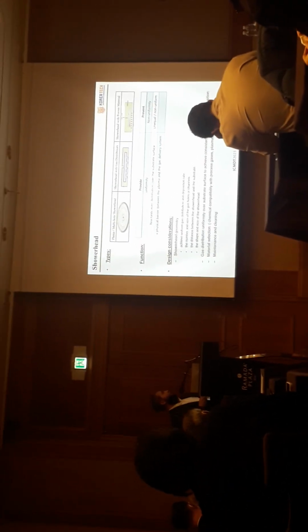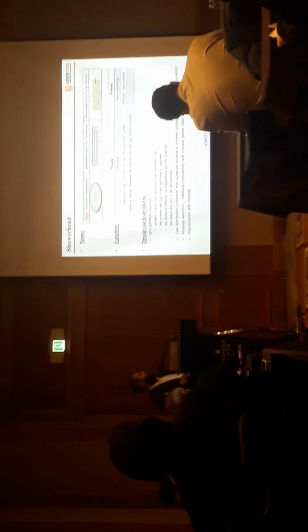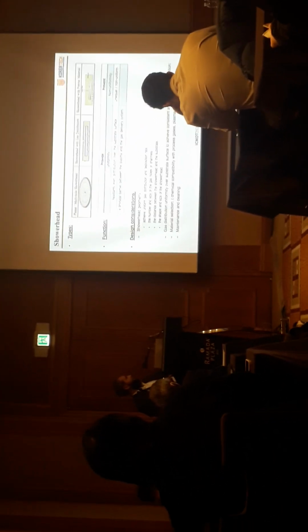The number and size of these holes, the distance between the shower head and the substrate, or the reactor gap, and the shape and size of the shower head and its nozzles all matter. Also, one of the considerations is the gas distribution uniformity over the substrate, as well as the material selection and the maintenance and cleaning, because fouling will build up on these shower heads, so you have to keep maintenance and cleaning in mind.